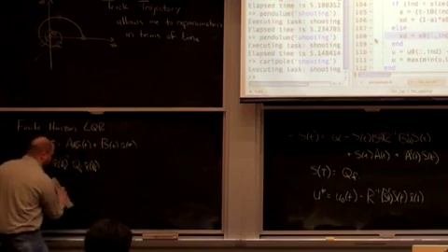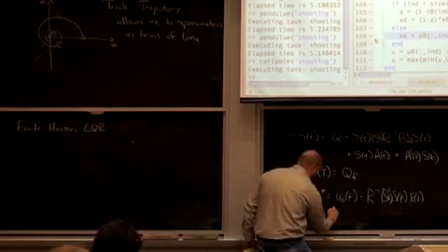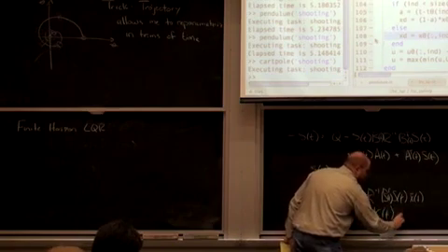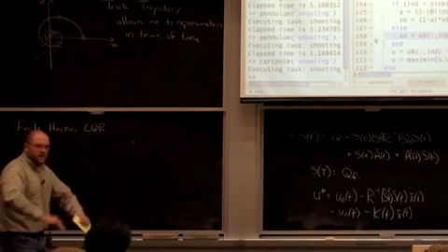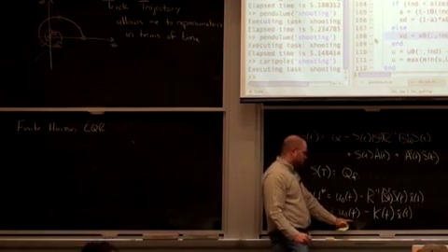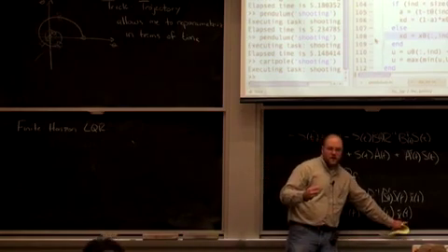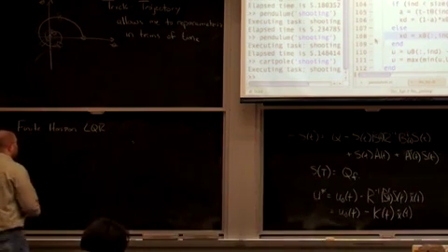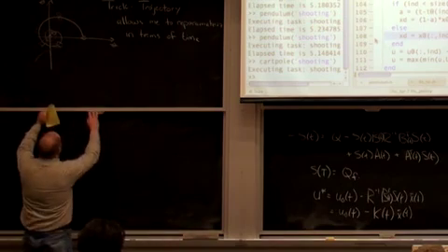So I designed a time-varying feedback controller, right? It's negative K(t) x-bar(t). I designed that ahead of time, and then from the initial conditions, I started simulating from 0, and I just played out my nominal trajectory marching forward with time, my feedback controller marching forward with time, and my aerodynamics marching forward with time.